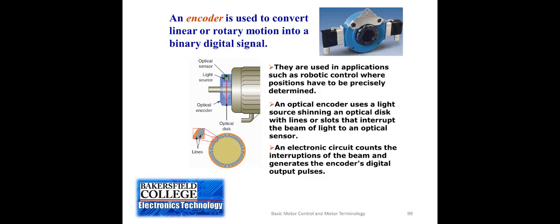Because if the motor was interfered with, if maybe there were some objects or something that caused the motor to stall a little bit, you still gave it the signal to move the full amount, but it actually did not move the full amount. That could be disastrous in robotics and automation. So there is usually some type of an encoder built into the motor itself, whether it would be a servo motor or a stepper motor. And that's the two motors that we will talk about in just a little bit.